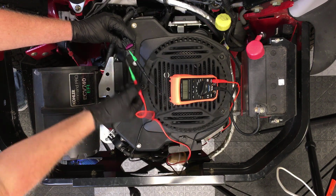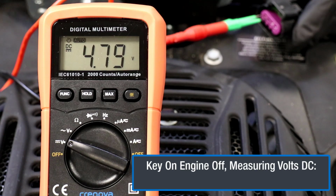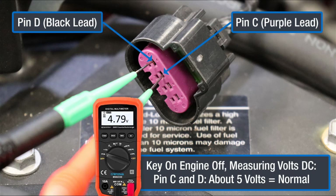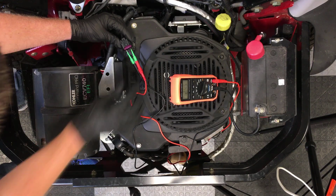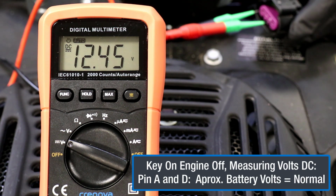With the key on and measuring volts DC, you should see about 5 volts between pin C and D. With the key on and measuring volts DC, you should see approximately battery voltage between pin A and D.